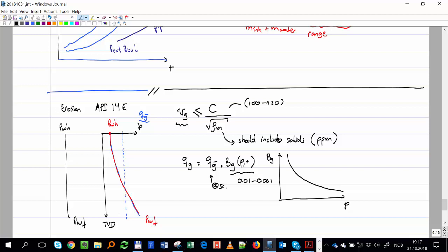But that tells you how the rate should go with depth, or with pressure. Here the pressure is low, therefore the rate should be higher. Let's say this pressure is bottom hole pressure and this pressure is wellhead pressure. The rate is increasing, right? The standard rate is constant, so if we plot now on the same plot, it will go something like that, QG local.